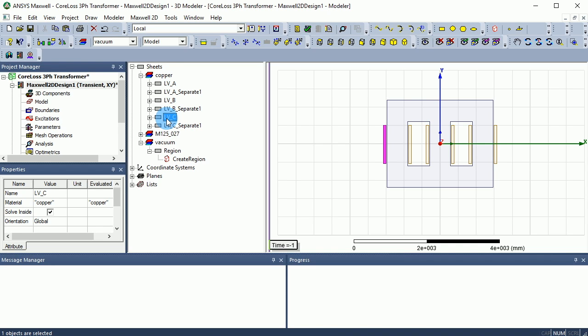So when you were trying to excite the coil, you just needed a cross section on one side of the coil and say run this amount of current on this side, and the 3D model will understand that this coil is part of a path. Therefore it would run the current around the coil, and you didn't need to define another side, the opposite side of the current.